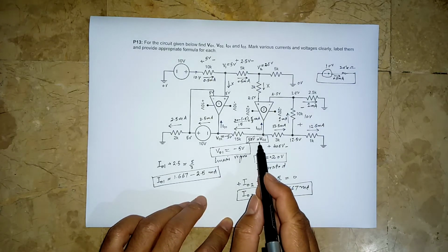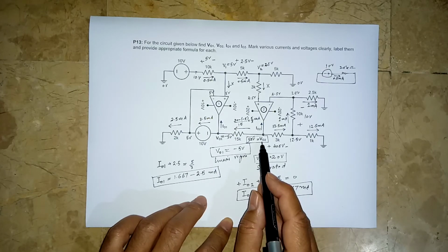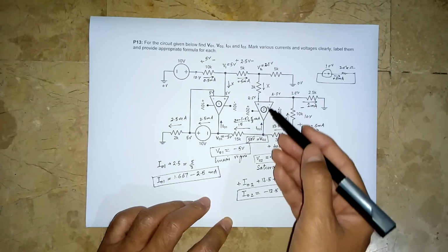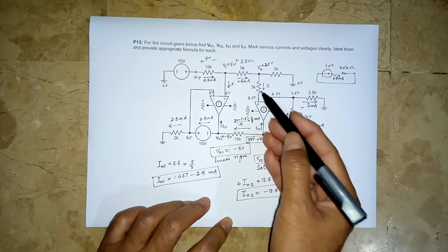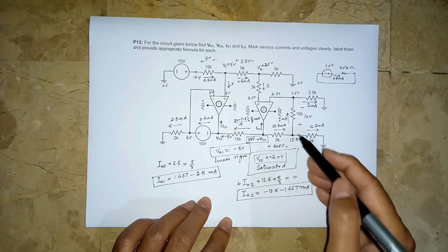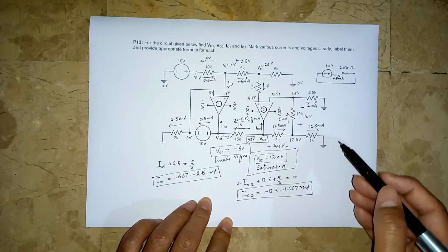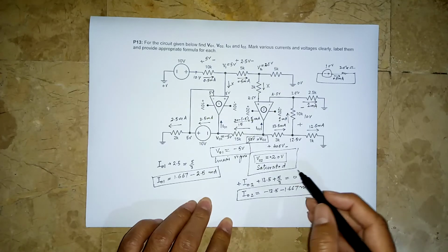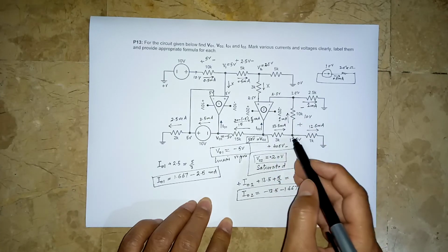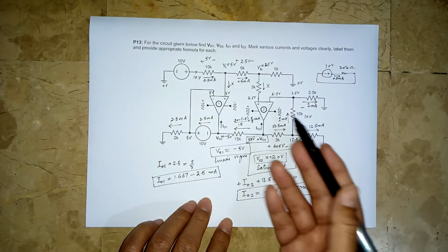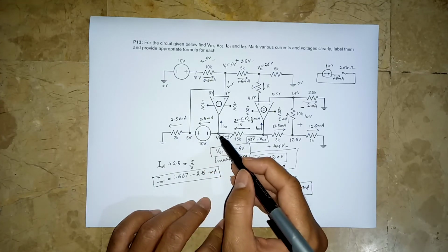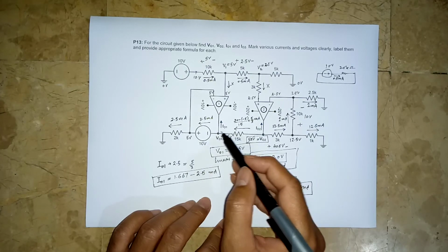The catch is if VO2 is 20 volts, since this op-amp is no longer operating in the linear region, it's in saturation, so all these characteristics do not hold. So there may be some current going in here. So actually, once you have found an op-amp to be in saturation, you cannot apply ideal op-amp characteristics at the input. And that basically jeopardizes this whole thing. So once you write that this is in saturation, we cannot for sure tell this current or this current or these voltages, because we don't know what the internal circuitry of the op-amp is. So whatever we are sure about is this voltage, and that's it. We are not even sure about this current or this current.